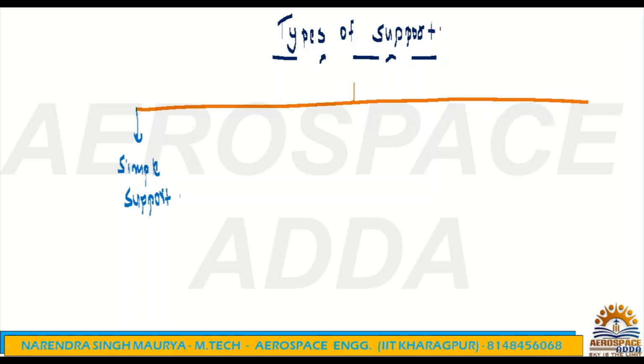In this case, the reaction at the support is at right angles. The beam is free to move in any direction, obviously, in the sense of x and y; in the vertical z direction it is not possible, but in x and y at least you can move. I will show the diagram, it will be more clear. It will also be able to rotate freely. There is no resisting moment. So one by one we'll see the types.